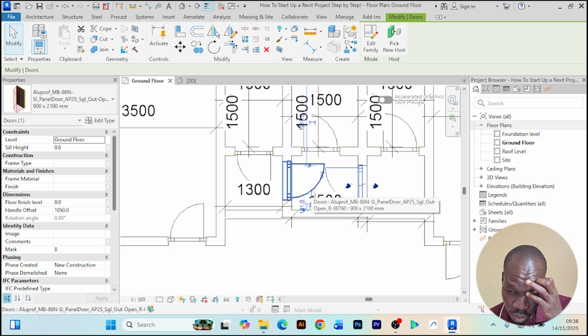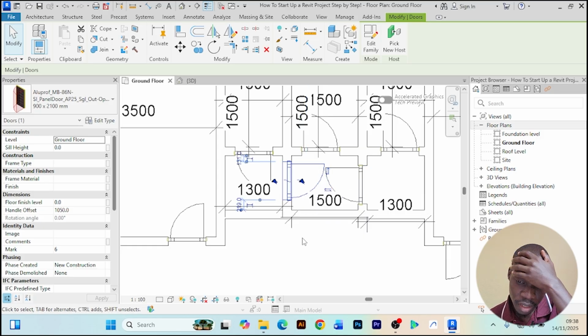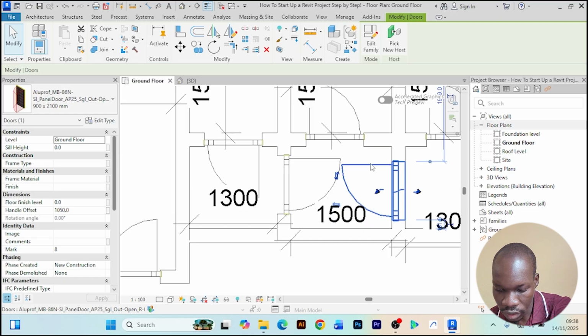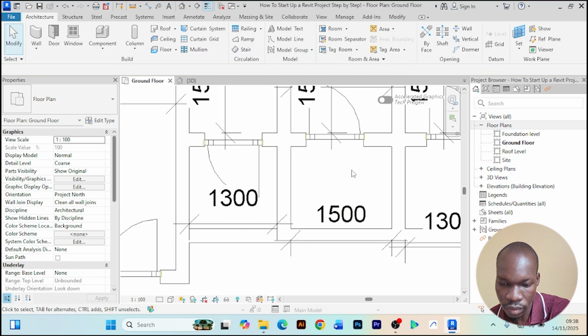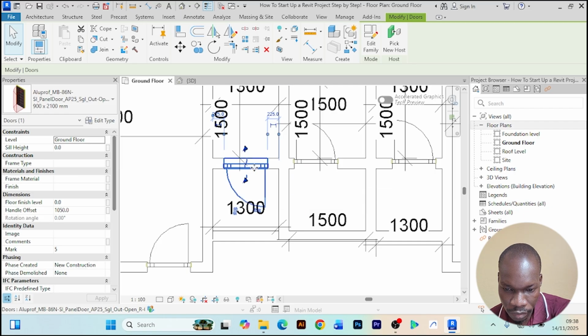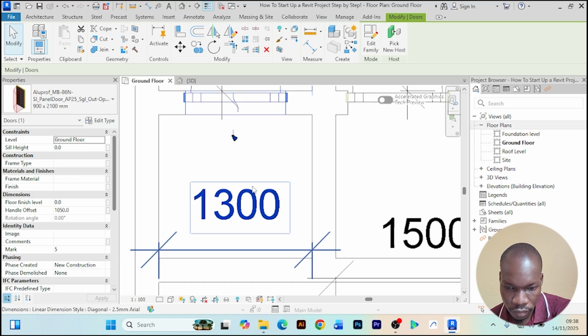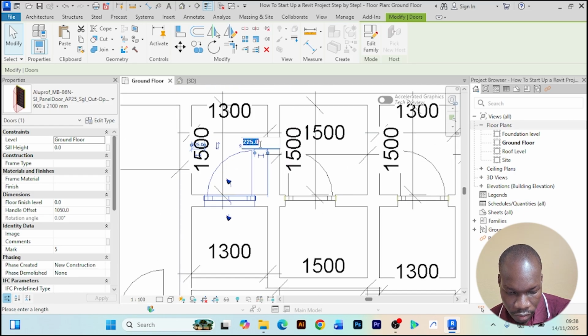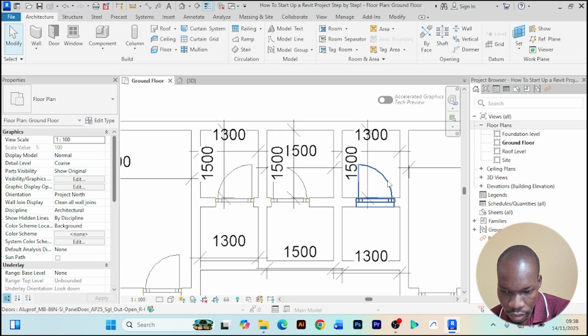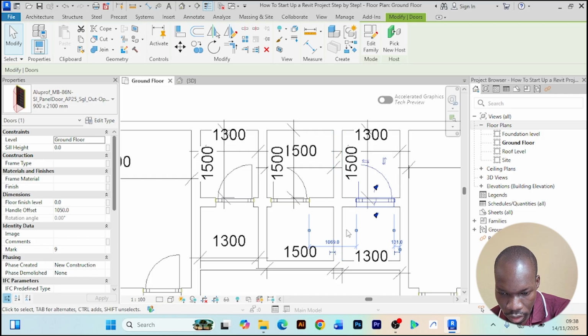now what I'm going to do, instead of having real doors here, we can create just open spaces for these areas instead of having so many doors. For now, this I can simply bring it here 100 millimeters. Then this I'll flip it inside. I'll have it here 100 millimeters. Then of course this is already flipped.